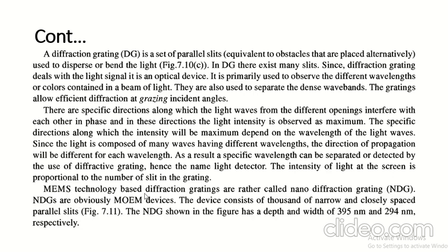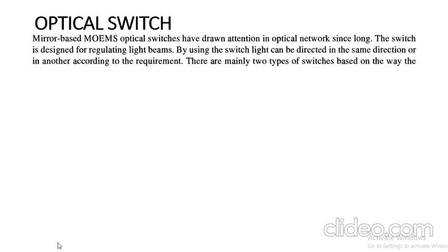MEMS technology based diffraction gratings are rather called nano diffraction gratings. NDGs are obviously MOEMS devices. The device consists of thousands of narrow and closely spaced parallel slits. The NDG shown in the figure has a depth and width in the range of 395 nanometers and 295 nanometers respectively.